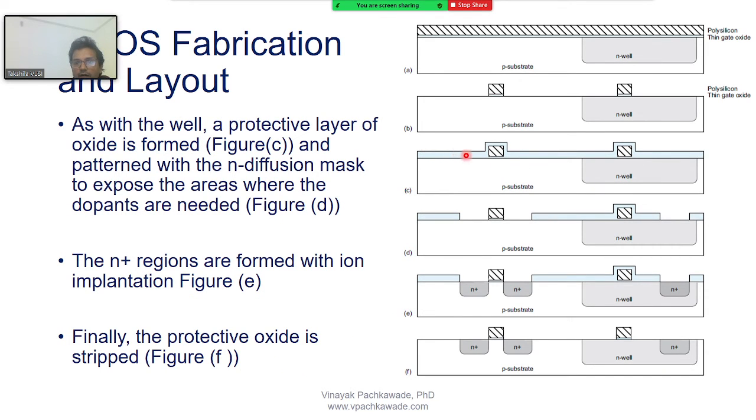So what I'm doing here now, I have grown the thick oxide here, and then can you tell me how we go from figure C to figure D? Look now at what I see in this area. Again the light fell, the photoresist got etched away, and then I put the wafer in the hydrofluoric acid, and the silicon dioxide got etched away from these areas, right?